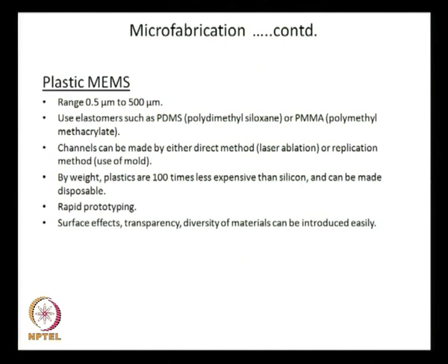And there are other effects that you can introduce, such as surface effects. Plastic can have surface effects induced in it. For example, it could be hydrophilic, it could be hydrophobic. It is hydrophobic, but if you treat it with plasma, it becomes hydrophilic. You can have a lot of chemical variation: if you oxidize the layer, then you have one property, and if you do not, then you have another property. You have those fantastic properties available with plastic material.